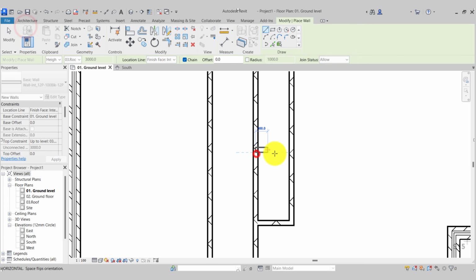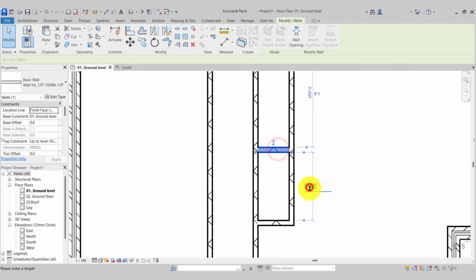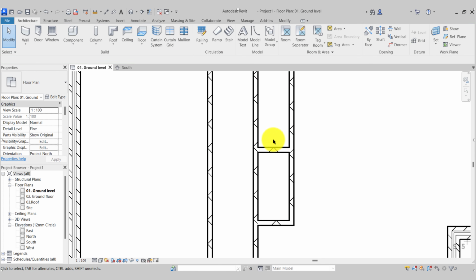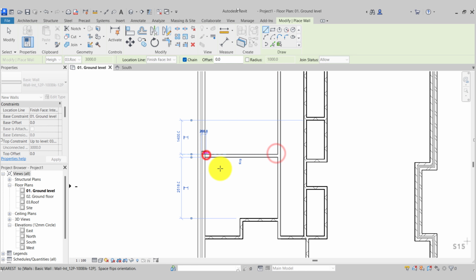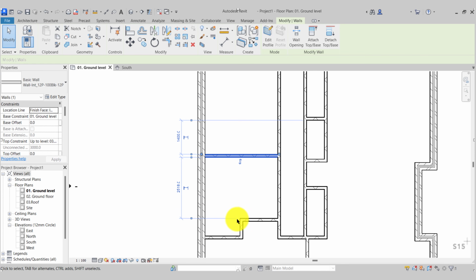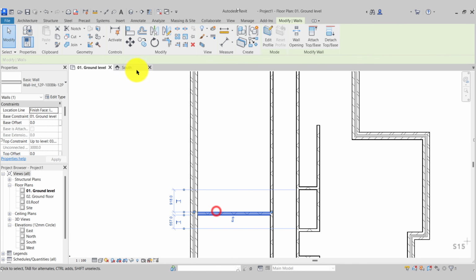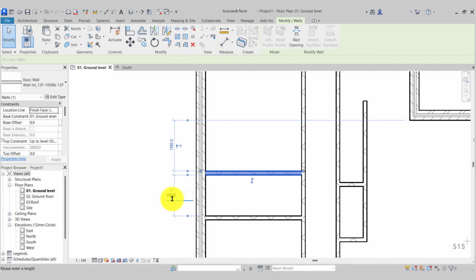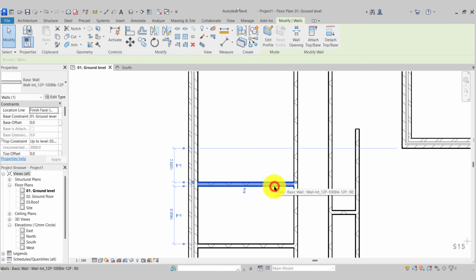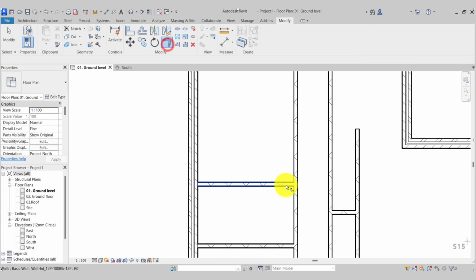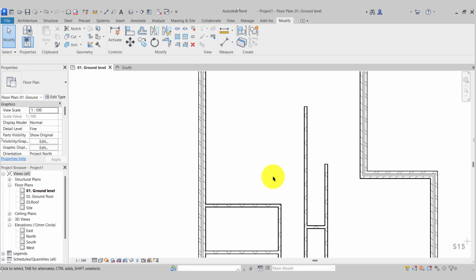We have another wall in between here, and between them is 1600. Coming over to the left, drawing the wall here, and it's 3000 from this adjoining wall here. And we can copy this up. And the distance between those two walls is 1800. And to tidy off this corner, I can select one wall, use the trim and extend to trim those walls there.